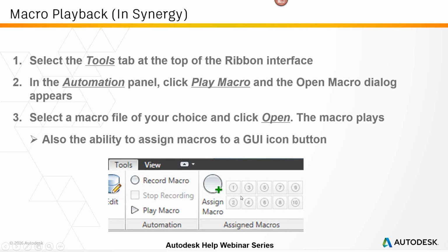You can save macros up to 10 in the interface, so that if you have ones that you always use, you may want to save those in these slots here, and you just click on Assign Macro and then which slot you want it in, and then you can utilize those. So you don't have to remember to even go in and navigate towards it. You can just click a button and it will do the macro for you.